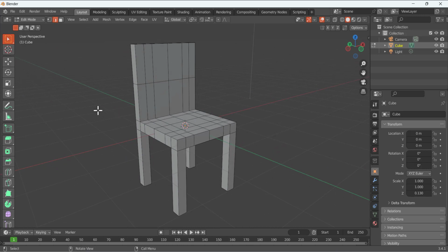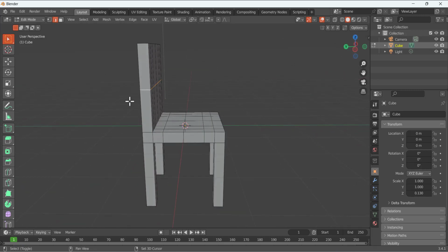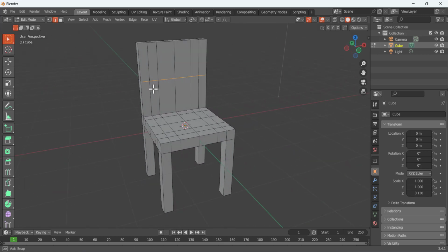So how I did it, you can manually select each one, then press the shift and select each one like that, and then rotate the model and select the other by pressing the shift. But if you want to select this whole thing in one selection, press the Alt on your keyboard and select this.